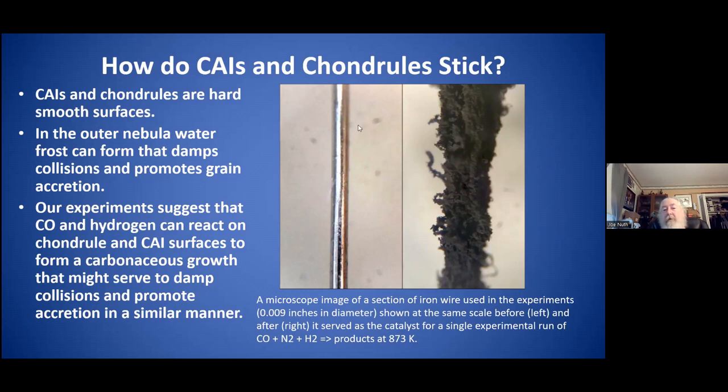And then, from a Fischer-Tropsch point of view, this would be completely poisoned because it would be completely covered by the carbon material that we were depositing. The mag silicate was covered much more slowly. But once it was, the catalytic activity that took place on the coating, the carbonaceous material, was much more efficient than what took place on the surface, and the rate took off.